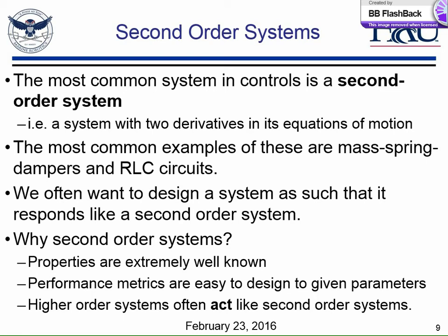And if you're a mechanical engineer, that means the mass spring damper. Or do I have any electrical engineers in the room other than Raul? Nobody? Then that's an RLC circuit, right? Those will give you exactly the same kind of something called a transfer function, which I'll get into in a second. So why are second order systems important for control systems?